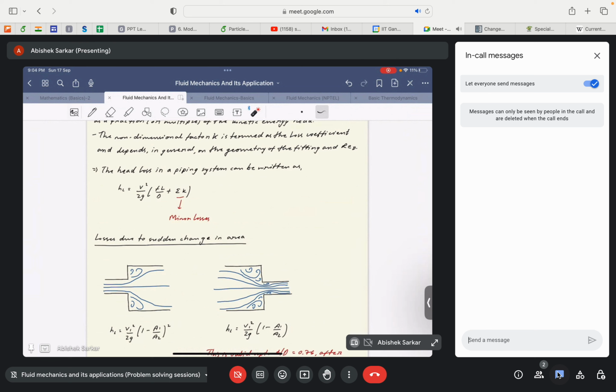So this kind of arrangement usually results in pressure losses. Why? Because of the flow separation, right? Since there is a sudden expansion or contraction, this results in flow separation. This will result in flow circulations in these regions, which thus results in energy losses, right? This is what we have shown in the case of the venturimeter. Why is there a gradual increment in the diverging section in the case of the venturimeter? That is to reduce the pressure losses and energy losses, right?